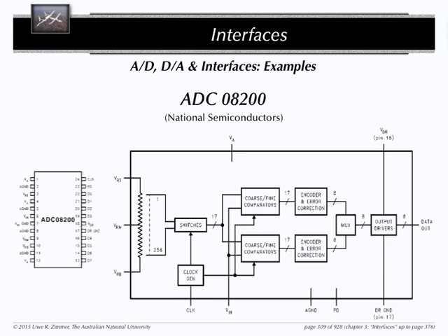There's just 8 bits falling out. Either you take those 8 bits into other parts of electronics of your own and further process that, or you need to put another controller in between this thing and your bus, so that the controller can respond to a certain address, communicate with this thing to get the data out in time, and put it on the bus in the right spot.